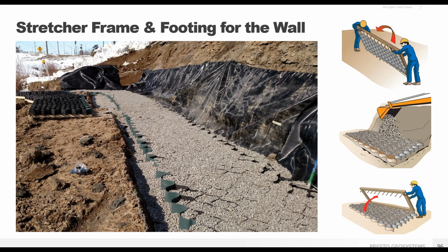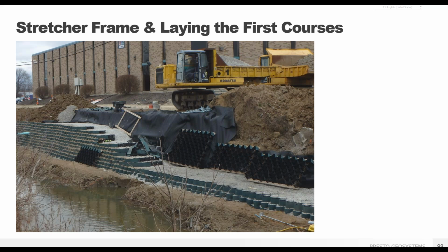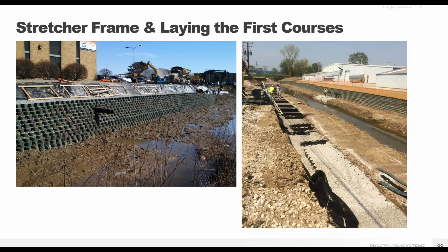Here we see the frames lifted away and reloaded, far left, getting ready for the next layer. Don't forget to compact each layer as you go. And the process repeats, going down the line, connecting panels side to side, and working in parallel for an efficient installation. And as one side of the stacked channel was completed, onto the other, also using stretcher frames.